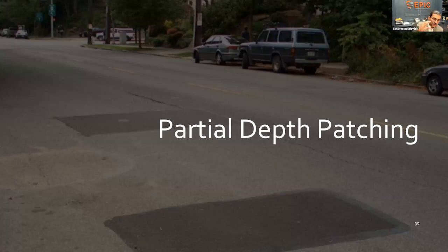This is just going to be in that top section, not the overall full depth of your slab, not cutting out like you would for, let's say, a new utility run. That may just be a uniform stretch across the roadway or parallel to the roadway, what have you. This is really just talking about that upper layer within even the asphalt, the friction course itself.